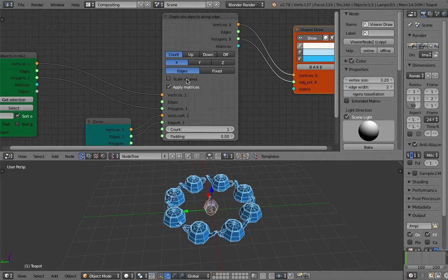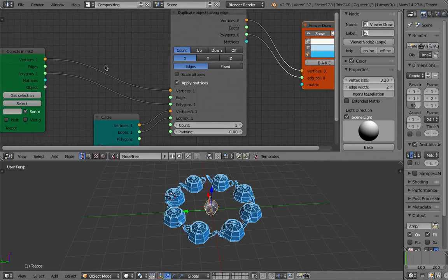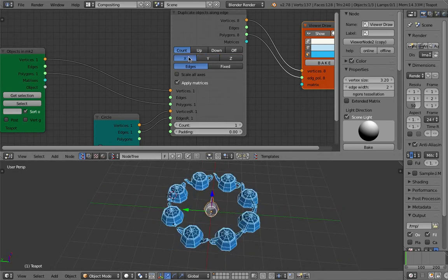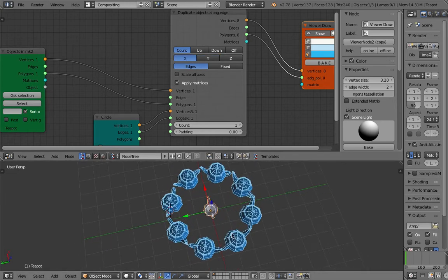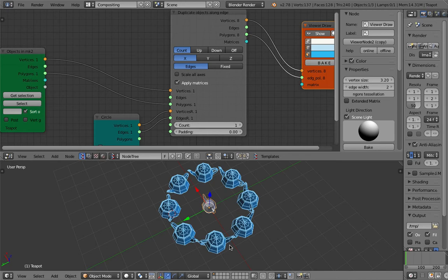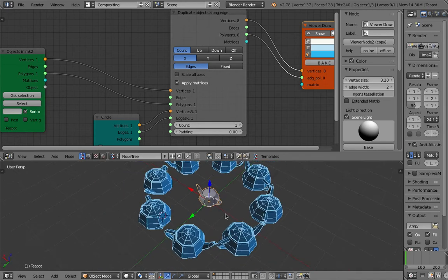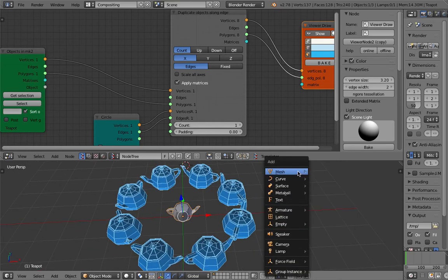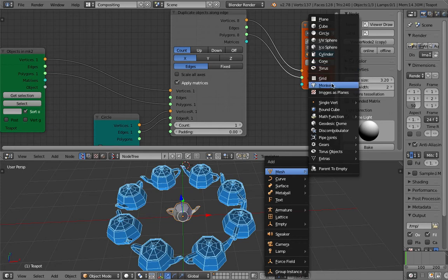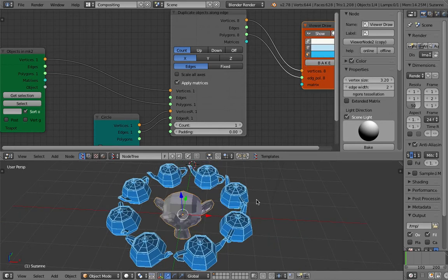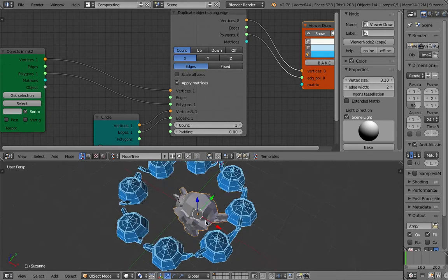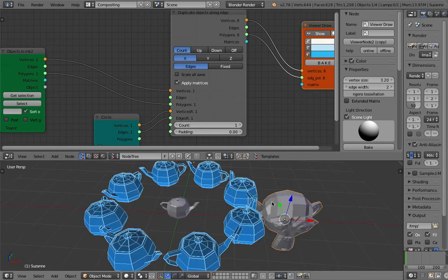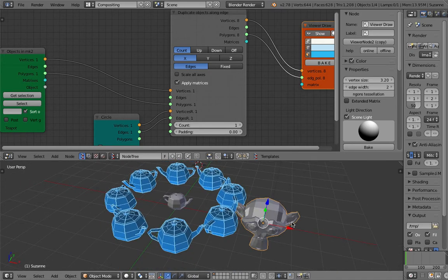Scale in all axes can be used. The X, Y, and Z, you see, is more clear now. X kind of gives the object the direction of the objects. So the teapot is facing X in that direction. I wonder if Suzanne is also the same. Suzanne by default, Alt G, Alt R. By default, Suzanne is facing minus Y axis, but teapot is facing in the Y direction.